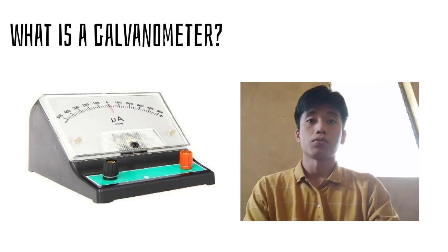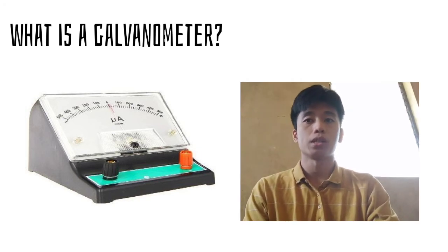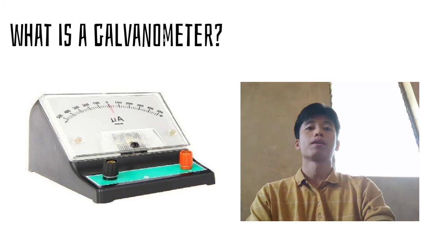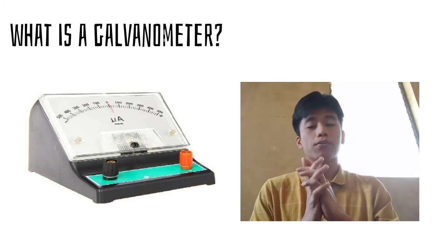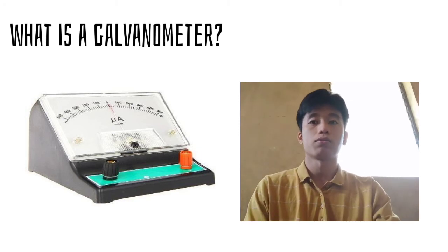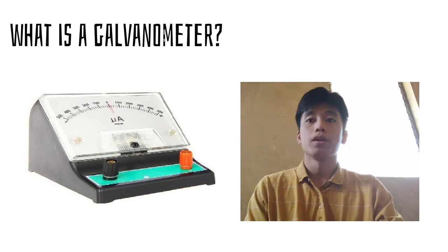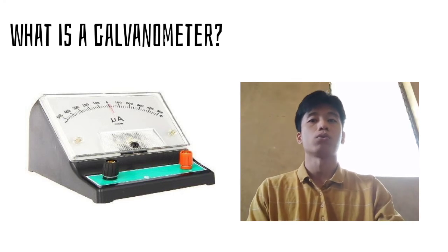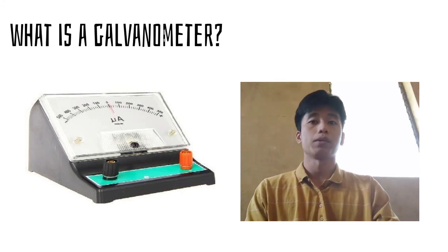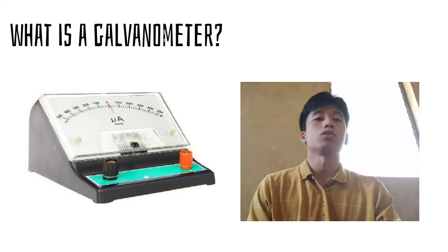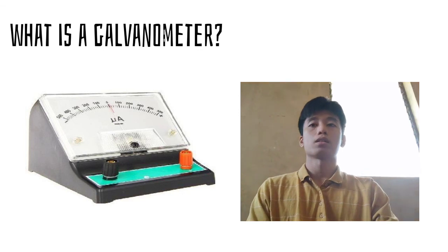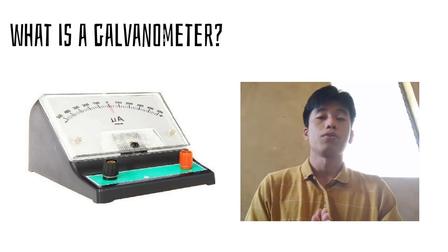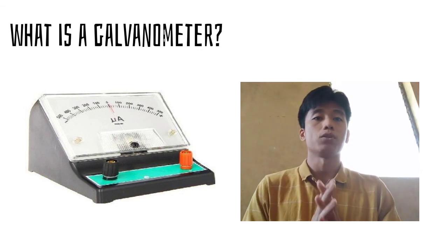The galvanometer was the first type of ammeter. It is used to detect and measure electric current. It is an analog electromechanical transducer which makes a rotary deflection response to electric current flowing through the coil. A galvanometer can read direct current flow. The magnetic field created as current flows through the coil acts on the spring, which will then move the needle indicator, pointing to the unit measure. Now, in the next slide we see here a video on how to use a galvanometer.